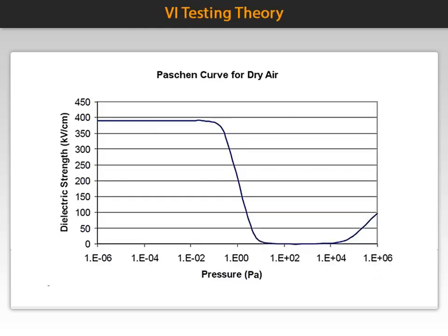In order to properly understand how MAC testing is applied to vacuum interrupters, it is important to first review some principles and theory. The high interrupting capacity of a vacuum interrupter is based on the physical principle discovered by Louis Paschen, which states that the dielectric strength of a gas is a function of the gas pressure, the distance between the two electrodes, and the type of gas. The result of this function is the vacuum interrupter breakdown voltage.